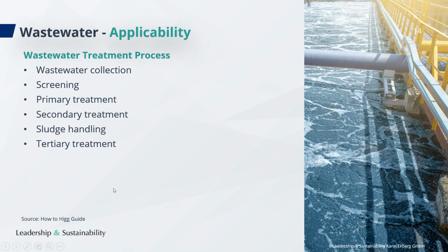And then we have the tertiary treatment. Similar to how a drinking water plant functions, the tertiary treatment stage can remove up to 99% of impurities using one or several of the following techniques: oxidation, electrolytic precipitation, foam fractionation, membrane technologies, electrochemical processes, ionic exchange, etc. There are lots of different processes that can take place here. And usually these processes are more cost and equipment intensive, but can then be adapted and adjusted according to the level of contamination that you have.